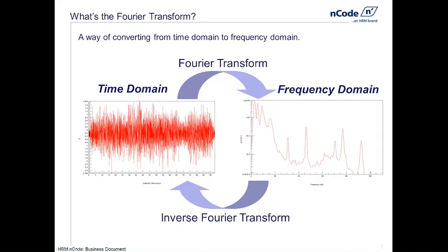So we're going to look at a lot of potential vibration data today in the time domain and in the frequency domain to help us better understand when we can take bulky time series data, maybe tens of thousands or even hundreds of millions of data points, and collapse it down to a nice compact frequency spectrum. When does that make sense in terms of the assumptions of the Fourier transform? And when does that meet our goal of being useful for engineering durability analysis?